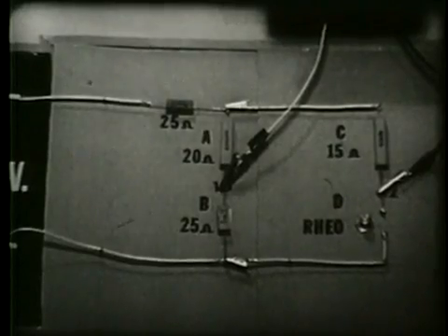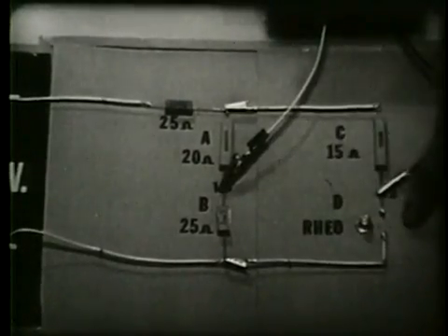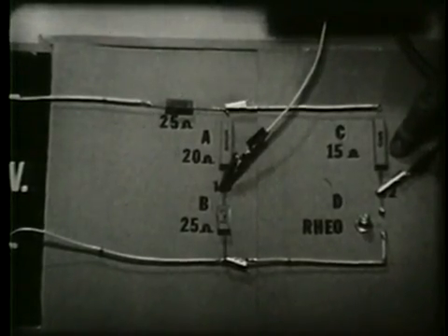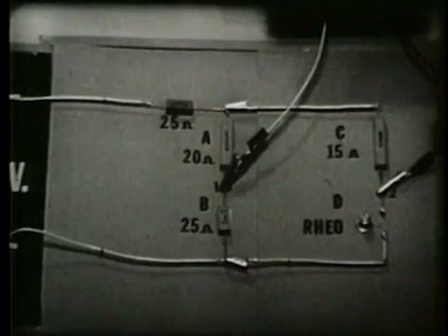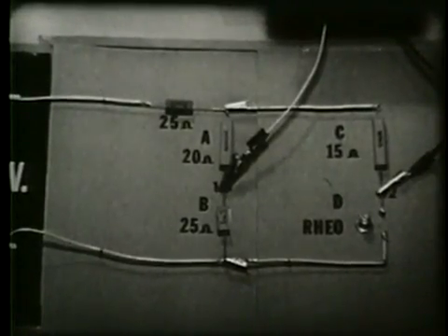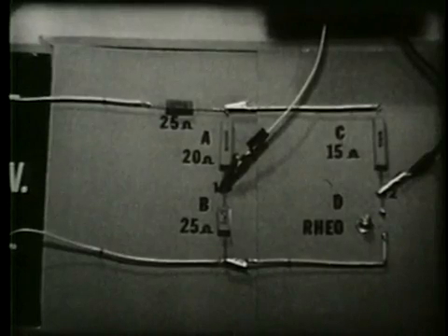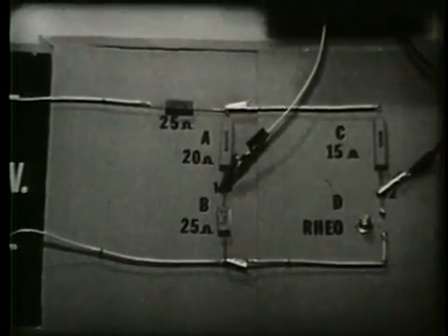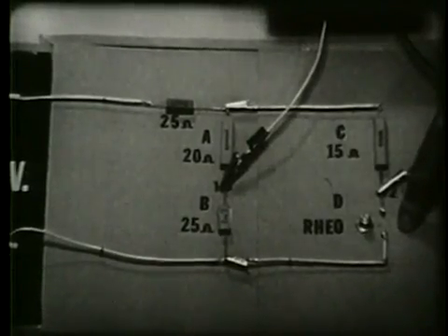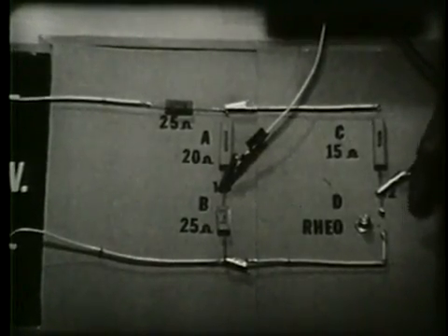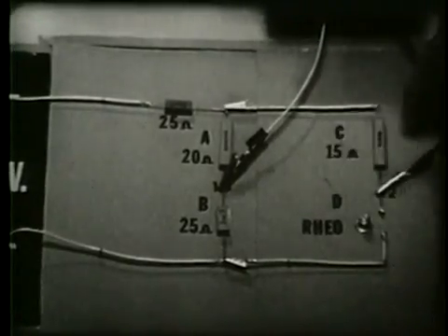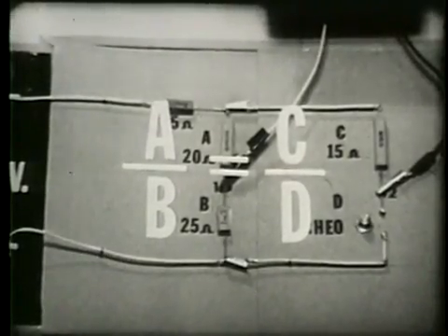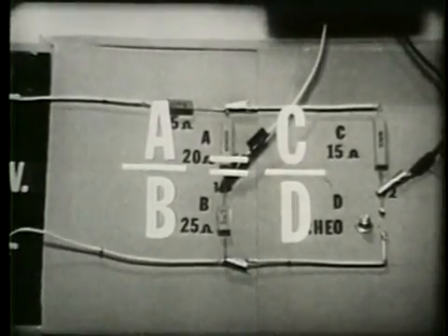When measuring a resistor, we may insert the unknown resistor in any position. In most cases, it is placed in the branch with the variable resistor. The variable resistor is then adjusted until we have 0 current through the meter. Now our ratios are correct. The variable resistor generally has a calibrated dial, so we will know the value of 3 resistors. We simply substitute these values into the equation and solve for the unknown quantity.